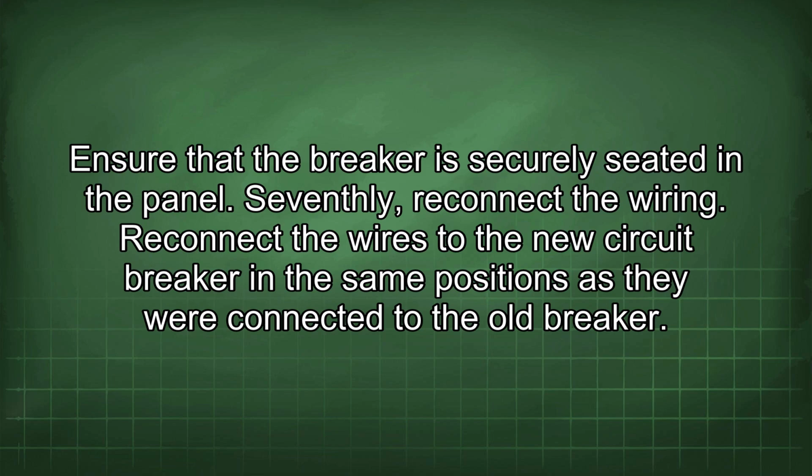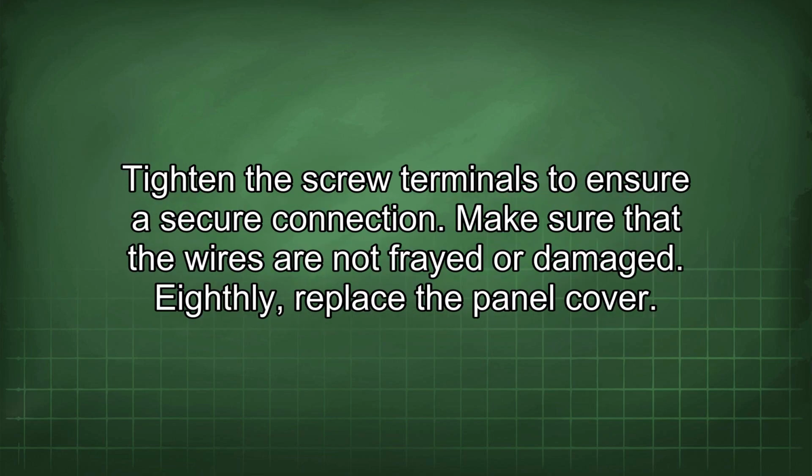Seventhly, reconnect the wiring. Reconnect the wires to the new circuit breaker in the same positions as they were connected to the old breaker. Tighten the screw terminals to ensure a secure connection. Make sure that the wires are not frayed or damaged.